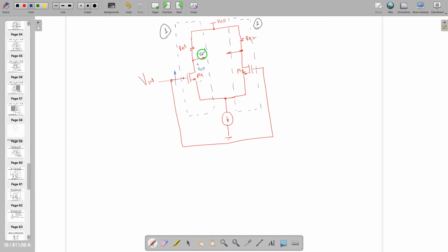So if this is increasing, this will increase a bit to get this transistor in saturation mode, because this VDS sat is nothing but VGS minus VTH, so it has to be higher than that. So VGS is playing a role over here in achieving the common mode voltage, or the voltage across any transistor. It's affected by the input transistor.